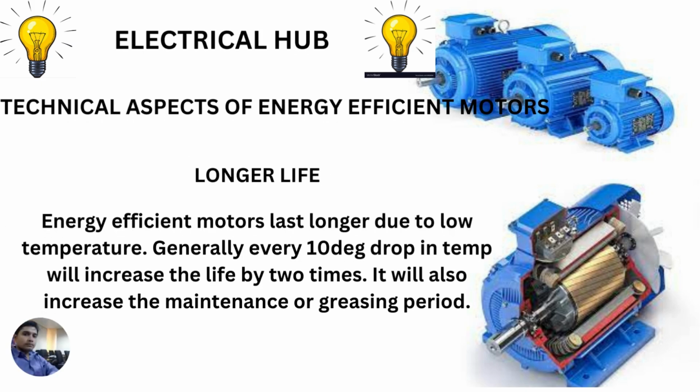Now, let us discuss the technical aspects of the energy efficient motor which benefit a motor in the long run. First is the longer life. Energy efficient motors last longer. Why? Because their operating temperature is lower compared to the standard motor.